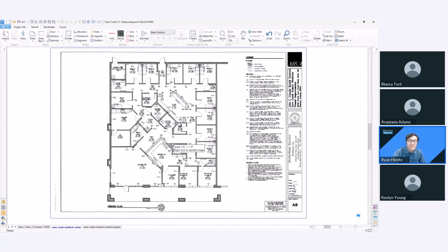One of the smartest time savers is to draw your rooms first and then create your materials second. You might ask why we do this. Well, the reason being is not every item in the finished legend ends up on the floor plan. So by drawing things first, we can focus on what is going to be actually used and skip loading up your catalog with unneeded or unused SKUs, right?